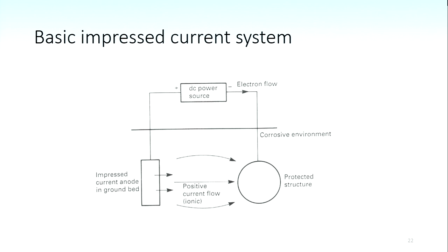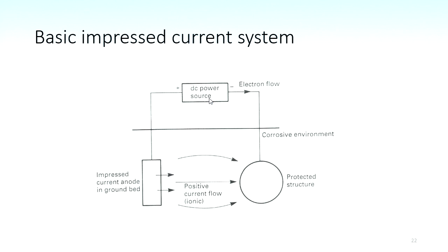One of the reasons why you don't need them closer together than that is because this is a coated pipe. All you're doing is the current flow isn't large unless you start getting defects in the pipe coating, and then it gets more exciting. So in your example, you just need one anode. This is a cross section and the pipe's going this way, so you can't see the next anode.